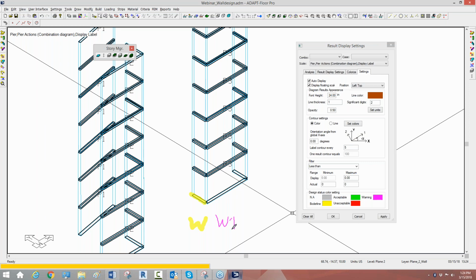So let's say this is wall 1, this is pier 3, and this would be top or bottom. So in this case, it's bottom. So that's one design cut for pier 3 at the very bottom. And then you have another design cut here that's evaluated, and a third design cut here. So there are 3 design cuts at the bottom and 3 at the top of this lower wall. And we just repeat that vertically for each unique wall ID.